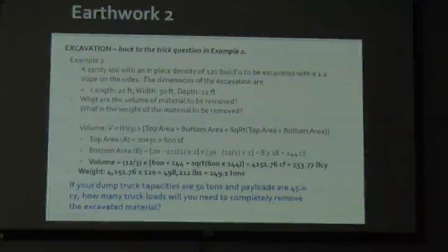Again, we come up with the same numbers that we had calculated earlier, because what I wanted to do was give you another dimension to the question. Remember, we said how much will be removed. Now we're asking how many trucks are going to be necessary to remove, or transport, the material. This first part of the question is about how much is to be removed, which refers to bank cubic yards. The next one is how much is to be transported, and how many trucks do we need, which would be loose cubic yards.